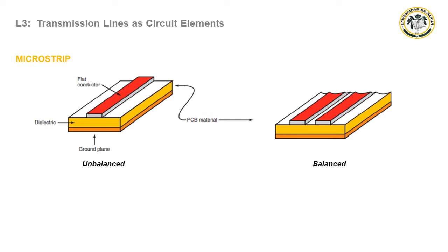A microstrip is usually 1/4 or one-half wavelength long. The ground plane is the circuit common. This type of microstrip is equivalent to an unbalanced transmission line. Shorted lines are usually preferred over open lines. Microstrip can also be made in a two-line balanced version, as you can see in the next illustration.